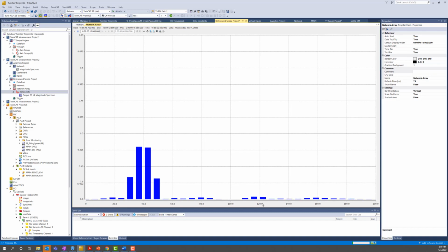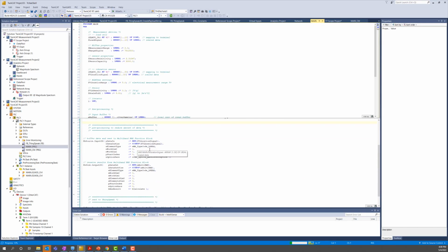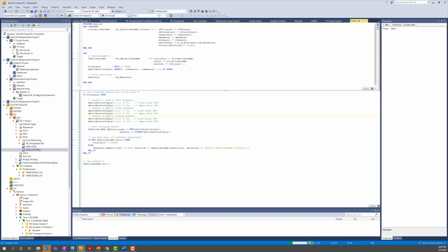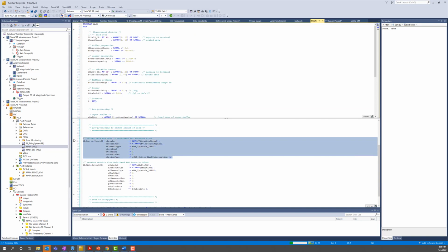Let us use this information to reduce the information content of the vibration signal. We therefore use the multiband RMS function block from our Condition Monitoring library. The function block calculates the FFT of a signal based on a defined time window and integrates the spectral power density of user-defined spectral bands. In this case, we define the spectral bands around the aforementioned base frequency, first and second harmonic. Hence, we reduce the information content from a 50 kHz signal to 3 values every 2 seconds.